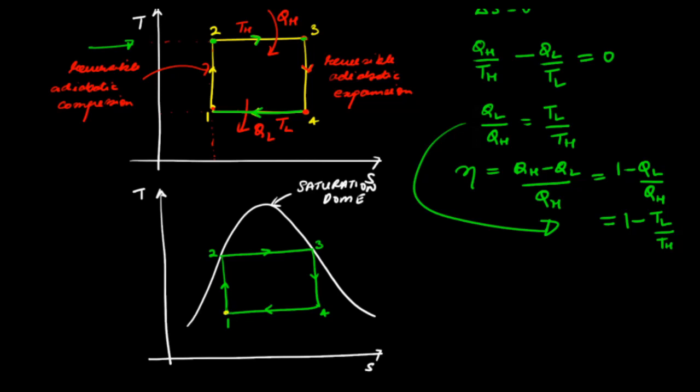If we choose this cycle for operating a Carnot heat engine, then at point 1 we have a liquid vapor mixture, and this liquid vapor mixture is compressed until state 2 is attained. At state 2 we have a saturated liquid. Thereafter heat is absorbed at constant temperature during vaporization from saturated liquid state at 2 to saturated vapor, that is at state 3.